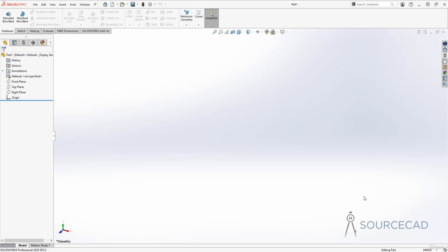This is the main work area where we'll make everything in SOLIDWORKS. So all the things that you make will show up here, and here on the bottom left side we have the axis, the user coordinate. So X, Y, and Z axis are here. Now this small thing, trimetric, is the kind of view which we have right now, though it may not be visible because we don't have any part or any object here, but it will be clear once we have explored the view tools.